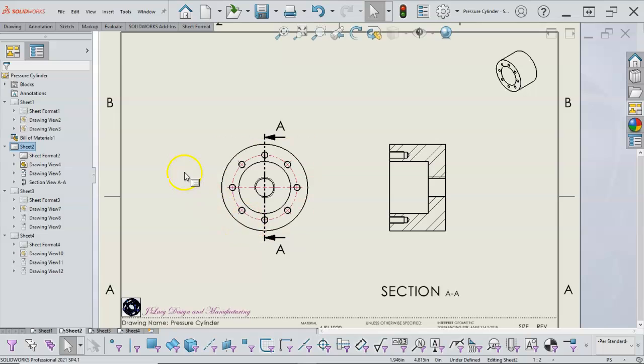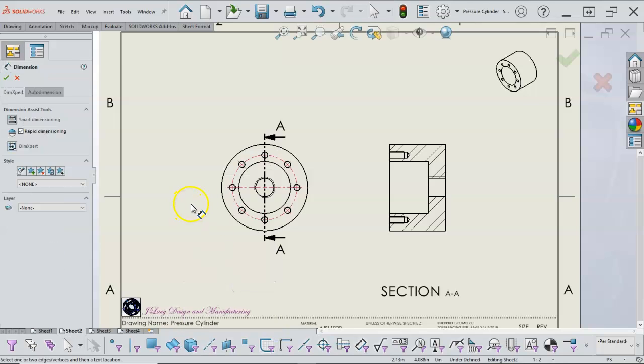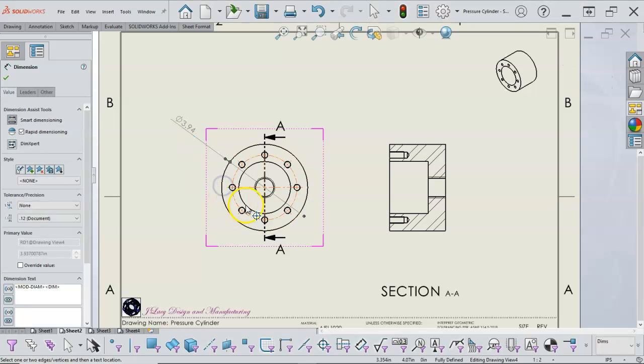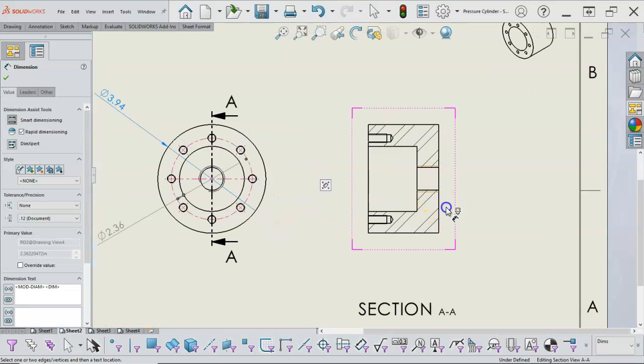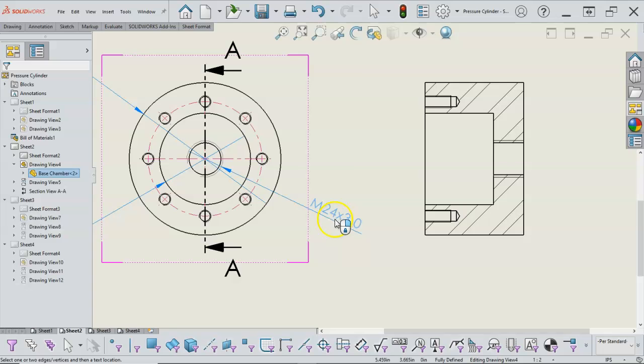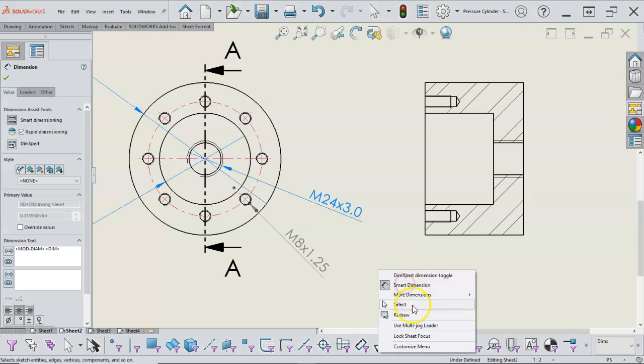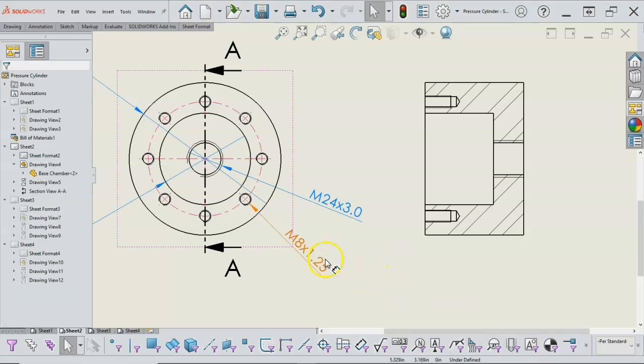All right, so my first pass on the dimensioning. All right, so finish the first pass, we'll go to the second pass. Have a diameter, an inside diameter. I did not have any luck with that picking up the cosmetic thread. It kept wanting to give me a length, where when I picked up the cosmetic thread over here, and the style stayed, so that looks pretty good. And the style stayed with the M8 by 1.25. So keep in mind that these are the smart dimension.